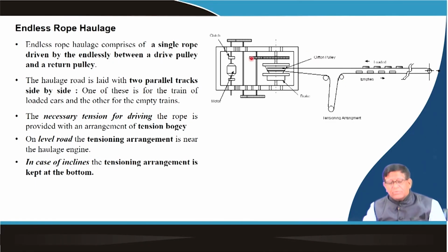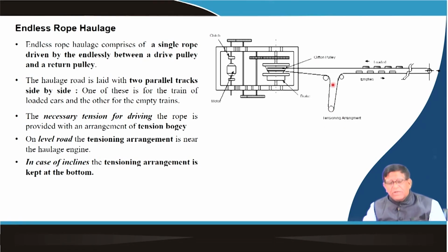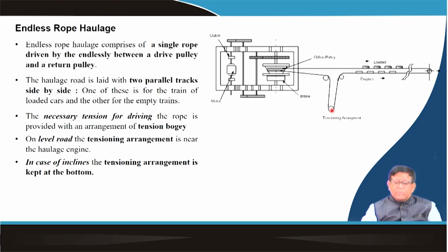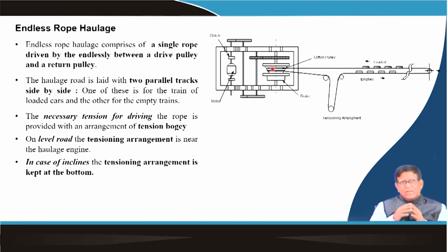In between, near the drive here, where the shift changing is taking place, you dig a hole over here and keep some weight, so that this will be under tension. When there is no load, it may come out because the tension is less, but to get the drive, you will always have to have this tension ready.